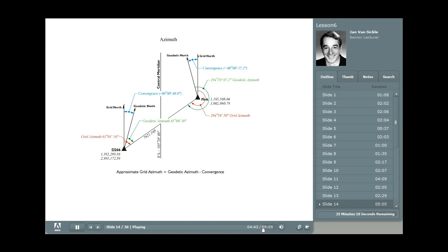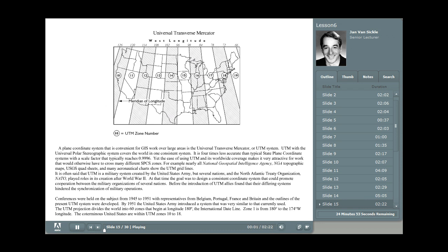So the bottom line is this. On the state plane coordinate grid, north is always parallel with the central meridian, but in reality, at the points on the Earth, north is along the meridian that passes through them, and they are certainly not parallel with one another, and certainly not parallel with the central meridian.